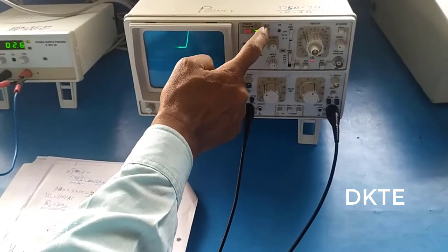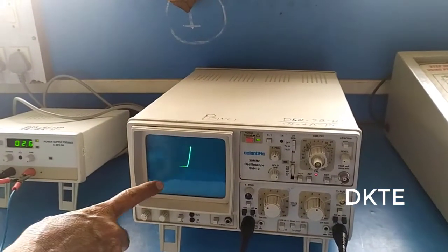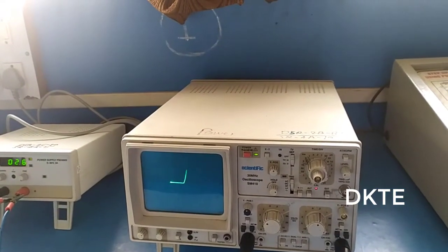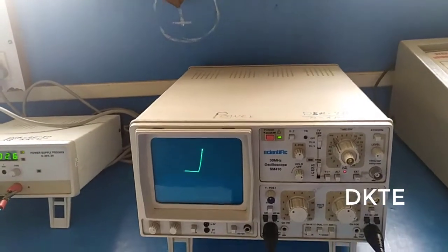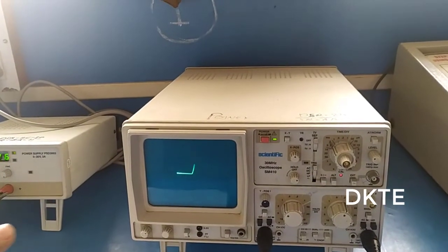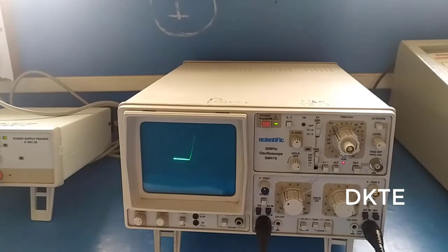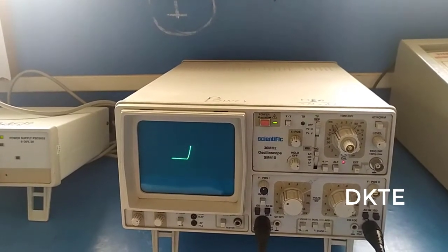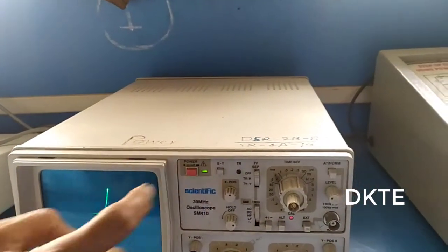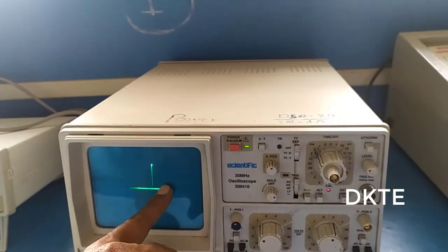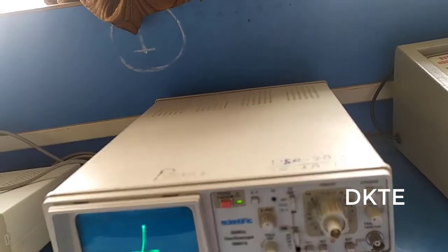You can observe this one. This characteristic is like a diode. It is acting as an uncontrolled rectifier, acting as a diode. The SCR is acting as a diode, an uncontrolled rectifier, as alpha is equal to 0 angle and beta is equal to 180 degrees conduction angle. And whenever the conduction alpha takes place, then this is the breakover voltage, this is where alpha takes place, alpha and beta. This is the breakover voltage. This is the VBO, and this is the SCR conduction state.